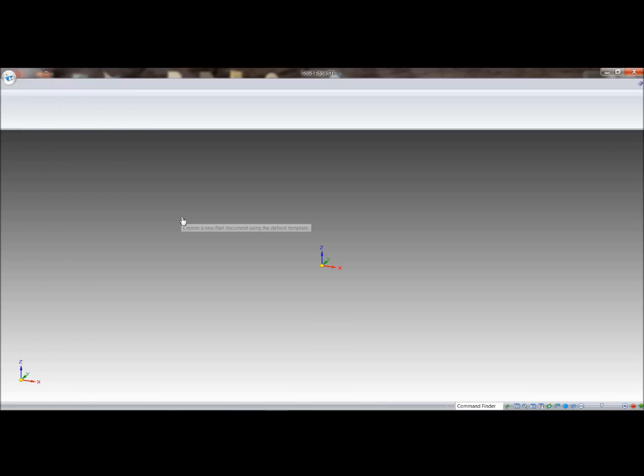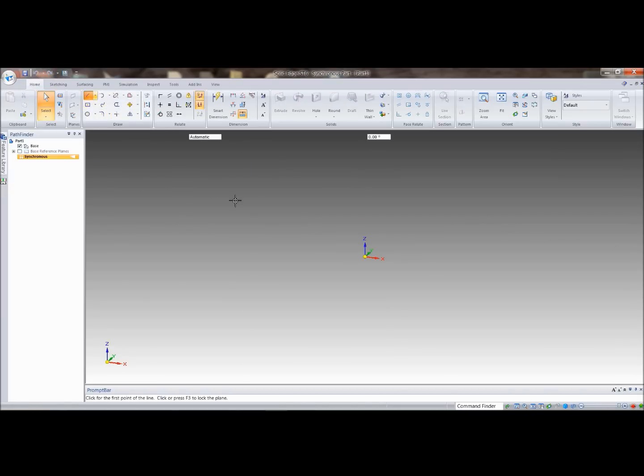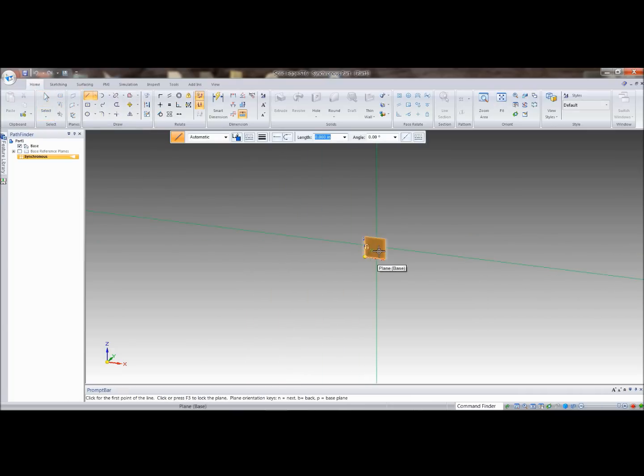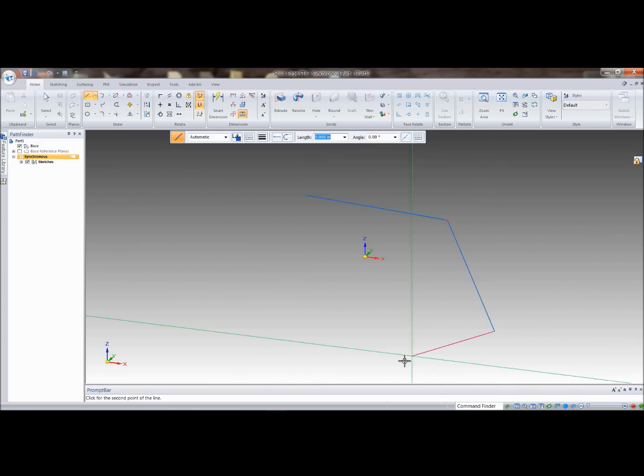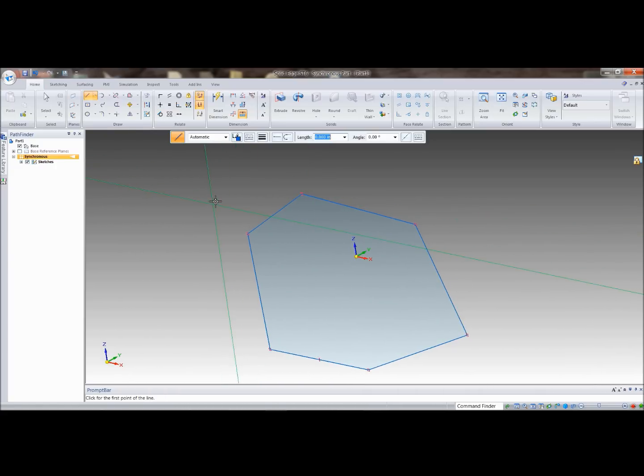Now, goal seeking has been in Solid Edge for many years. If you didn't know it, in ST, oh gosh, no, it was way before ST came along. It was in the drafting portion of Solid Edge, and it would allow you to do goal seeking on a 2D basis. So if you had a sketch, you could do a goal seek on, for instance, the area within a sketch, perhaps the perimeter of a sketch. It would allow you to vary a dimension based on a goal that you're trying to achieve for a certain dimension.